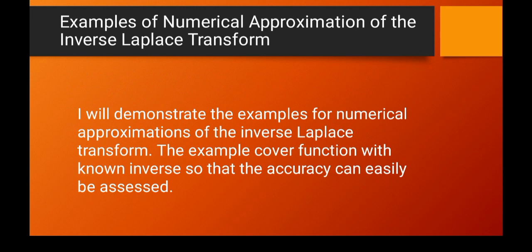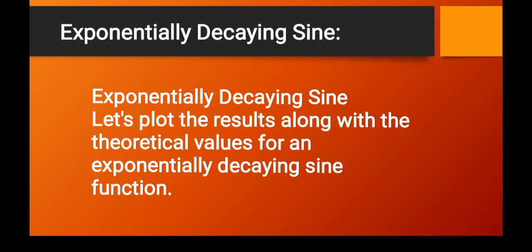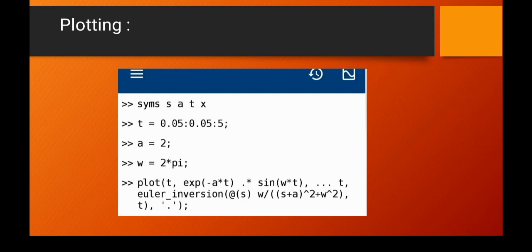So an example of numerical approximation of inverse Laplace transform is the exponentially decaying sine. Let's plot the results along with the theoretical values for the exponentially decaying sine function. First, I have used the command syms, in which I have defined the variables I am going to use.